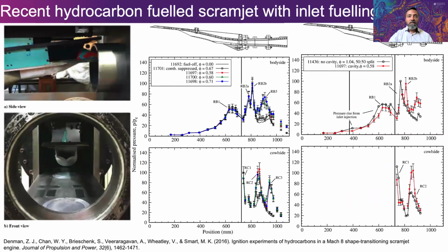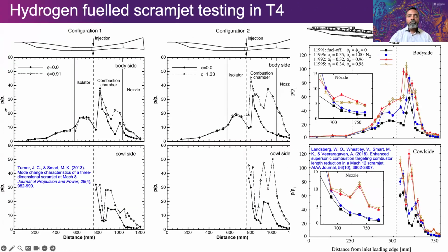So the front part of the engine looks like this. You can't see it in this view, but you can appreciate that it's projecting out towards you, and the combustor actually starts downstream of there, and the inlet starts to close down into an elliptical combustor. Okay, so coming back here, so therefore you have the top and the bottom are not identical, they're not symmetric. It's an inherently three-dimensional flow field from the inlet onwards.